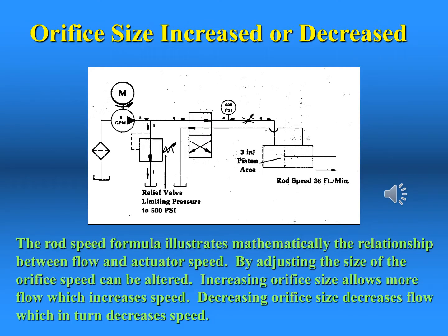For demonstrative purposes, we will assume the flow rate is correct on this slide. The cylinder rod moves at a speed which is controlled by the amount of oil coming from the hydraulic pump and limited by the restriction of the flow control. If 4 GPM go to the cylinder, the remaining 1 GPM must go back to tank.